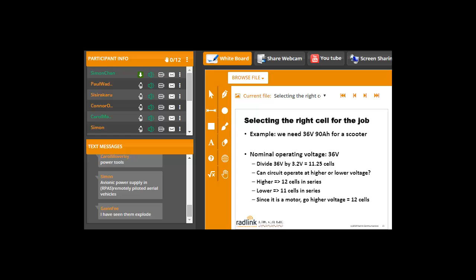Not only that, the largest size also allows you to have a higher charging and discharging rate. So you divide 90 by 5 amp hours, which is the 32650 cell that I've got here, and the calculation tells you you can have 18 cells in parallel.